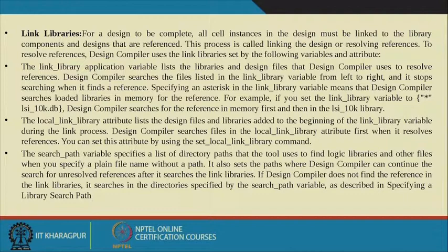Okay. So, suppose I kept all this library information into a single directory or path. If I mention in the tool that my library search path is this one, and you find this library, then automatically it will go to that particular directory, search, and incorporate those libraries into the Design Vision environment or Design Compiler environment.